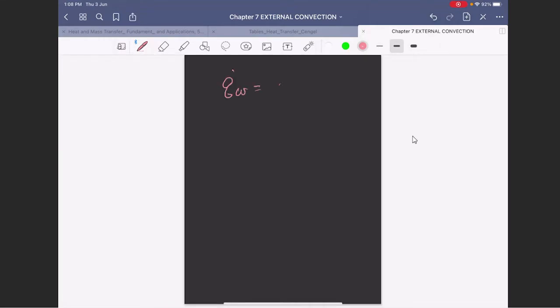That is why Q of the windshield equals Q of the outside air. You know this value, 1035, the Q of the windshield, because this is conduction. So k, T surface in minus T surface outside, divided by delta X. From here, you can determine the inner surface temperature of the windshield.